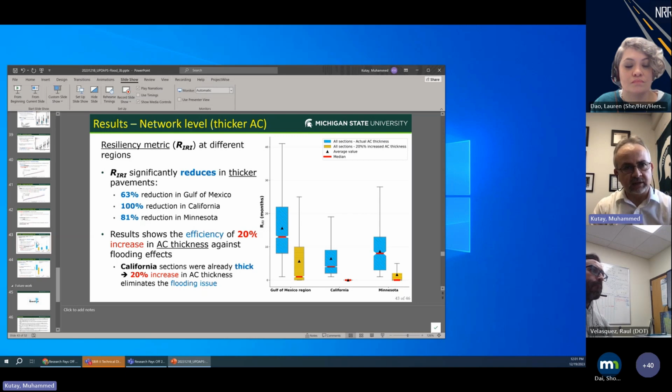But one thing that I'd like to emphasize, what Farhad said, is the use of geosynthetics in the unbound layers. I think that's something that we have been working on. There's a UTC project. So we would like to investigate that further, because increasing the thickness may be expensive and also may not be the best idea ever. But improving the properties of the unbound layers, let's say putting geogrids in there or some other geosynthetics in the right locations, might be a less expensive and more reasonable solution.